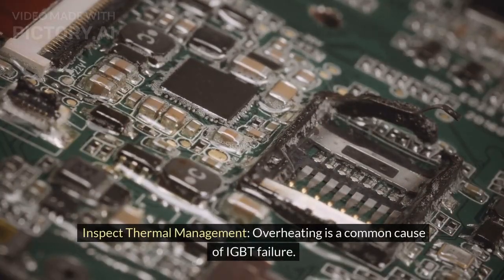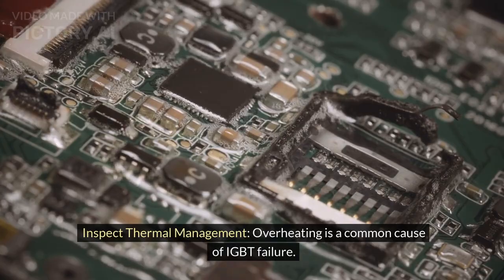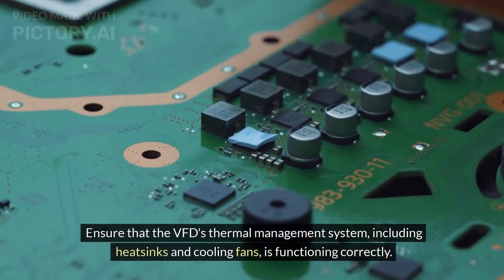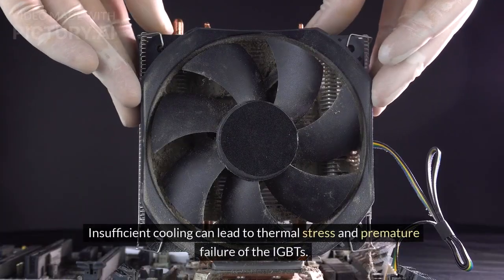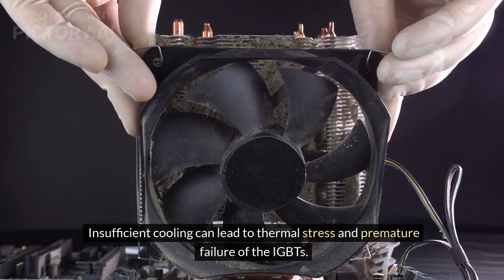Inspect thermal management. Overheating is a common cause of IGBT failure. Ensure that the VFD's thermal management system, including heatsinks and cooling fans, is functioning correctly. Insufficient cooling can lead to thermal stress and premature failure of the IGBTs.